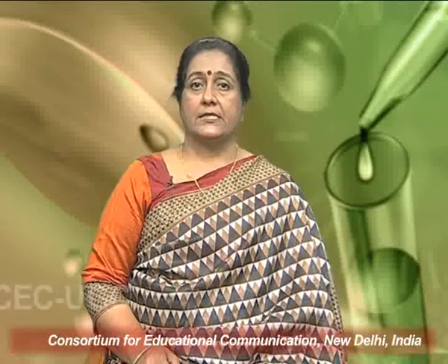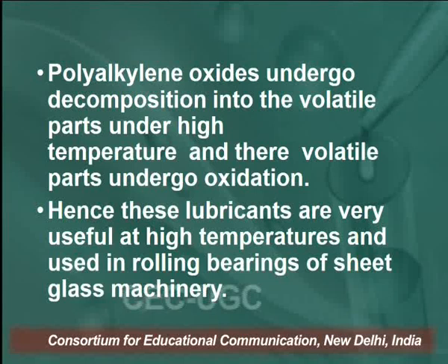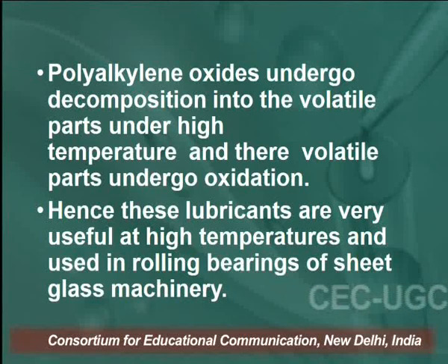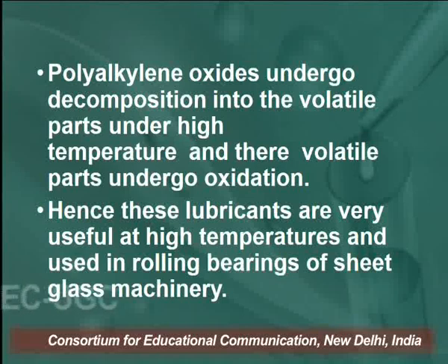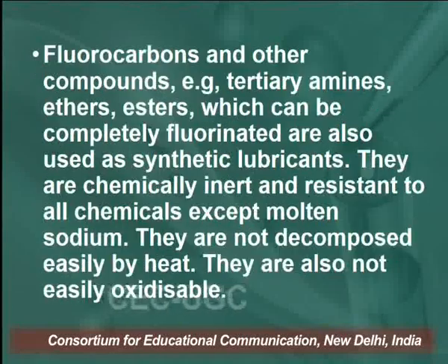Polyalkylene oxides undergo decomposition into volatile parts under high temperature, and their volatile parts undergo oxidation. Hence, these lubricants are very useful at high temperatures and are used in rolling bearings of sheet glass machinery.